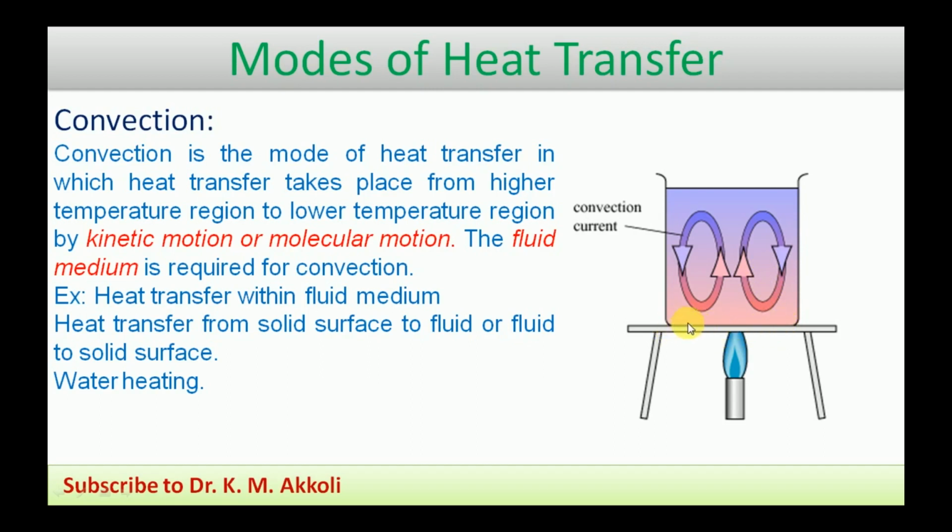Then heat is transferring through the bottom wall of that pan to the inside water. Only the layer of this water will get heated initially. Then the surface water, whatever is there, will not get heated; its temperature is lower, and there is a temperature difference between these two. Due to that temperature difference, there is a density difference between the fluid at the bottom and at the top. Density decreases if the temperature increases. That's why there is a density difference.